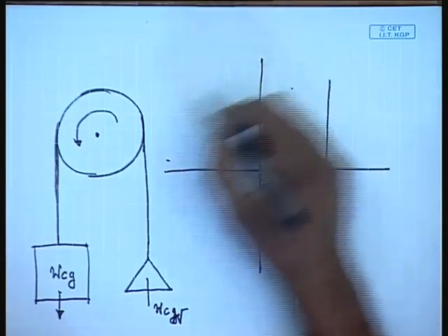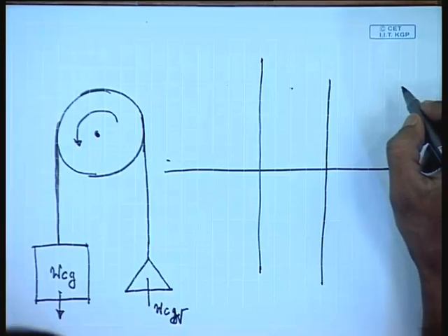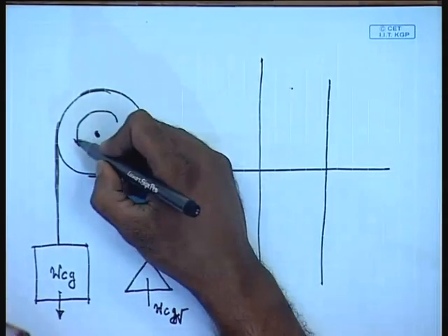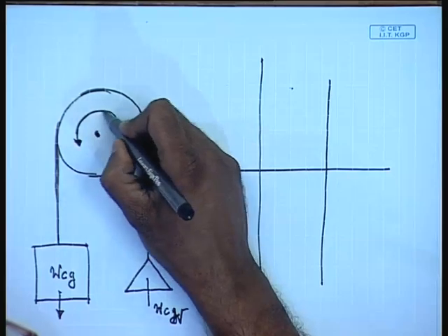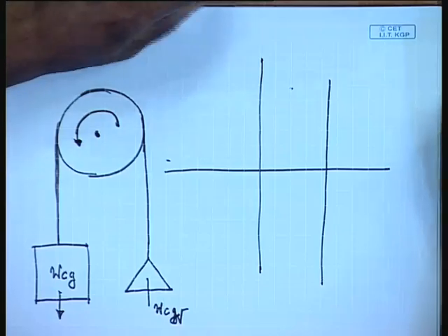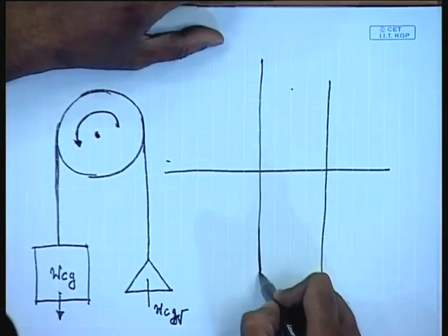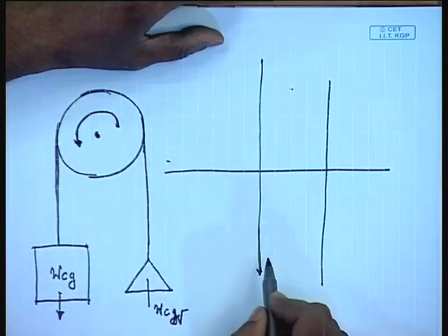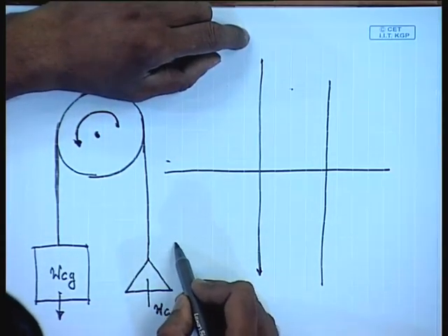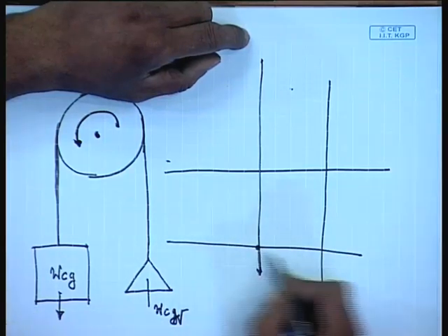However, now the motor rotates in the reverse direction and it is necessary to control the speed, in which case what we do is reverse the terminal supply and make the motor operate in this fashion.